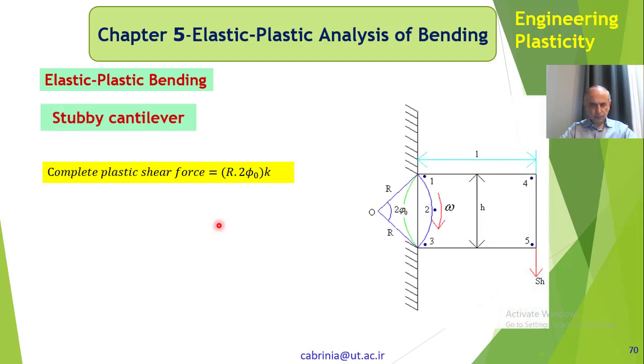Now, in this page, I am considering a stubby cantilever. What is a stubby cantilever? A stubby cantilever is a cantilever like this, which has a length and depth which are comparable. Okay, that H and L are comparable to each other. That means their dimensions are near.